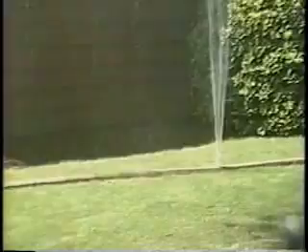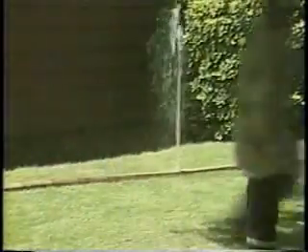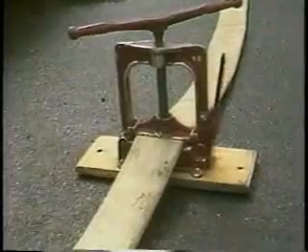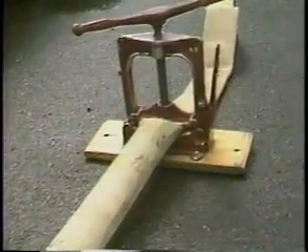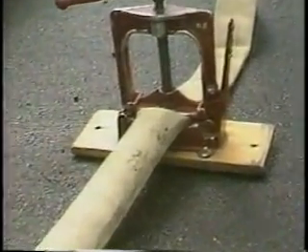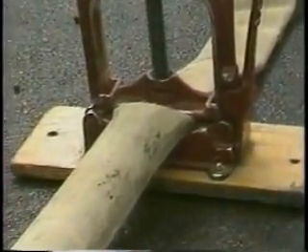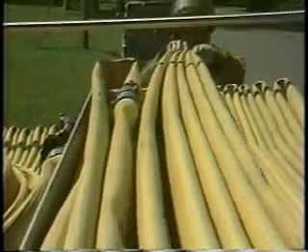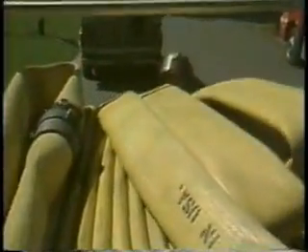As soon as the hose or coupling failure is spotted, immediately shut the line down by shutting down the apparatus pump or placing a hose clamp on the line. Small diameter lines may be bent in half to stop the flow of water. Lengths of hose from the apparatus hose bed are coupled in to replace the damaged hose or coupling.